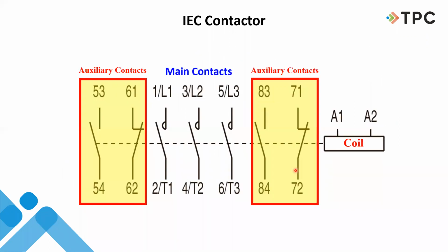This is kind of power and controls all together, but I want to make sure that you understand, no matter what it is, odd numbers are the source, even numbers are the loads. And I'm going to tell you, Europeans will run a wire 3 foot longer than it has to be to make sure that it gets connected to the right place. They do that so that they know where the power is going. That's why they have all their numbers on their devices, so that it makes it really easy to know where things are coming and going to.